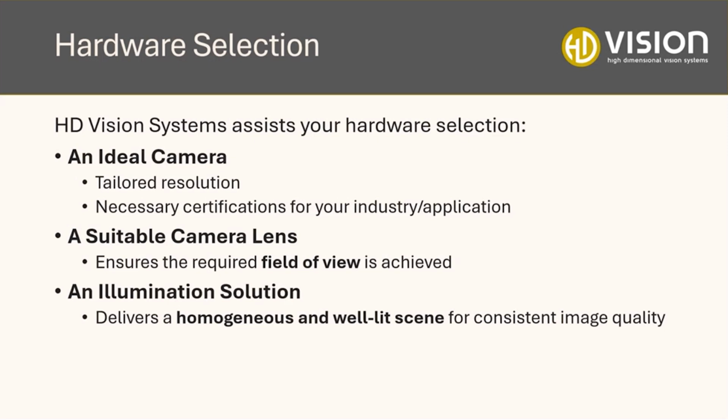For example, it can be distracting or unwanted to have a flashing light in a production line where there are people walking around. So it might make more sense to have a light source that's constantly on. On the other hand, if you have a fast moving object, you might need to use a flashing light, because otherwise you can't capture this object in time.